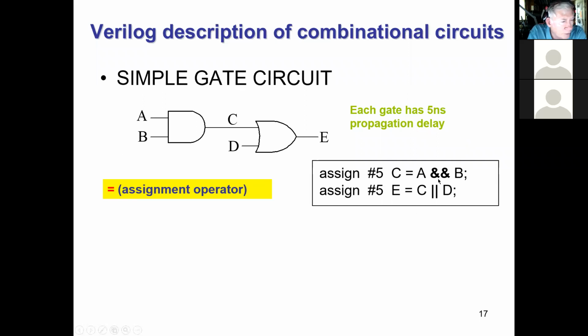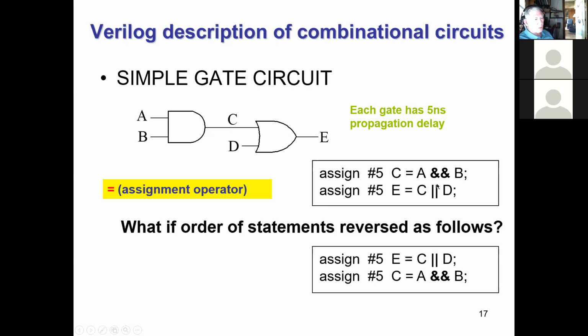I guess this is kind of convention, but I don't like it. I think you might as well just go ahead and use the bitwise operator, because what if you go back and redefine A and B as vectors, and then you forget to go change your logical operator to a bitwise operator? Might as well just have a bitwise operator there. Different people have different theories about this, but I like to use the bitwise operators where you actually mean bitwise, even if they're single bits, and you could use the logical operators.